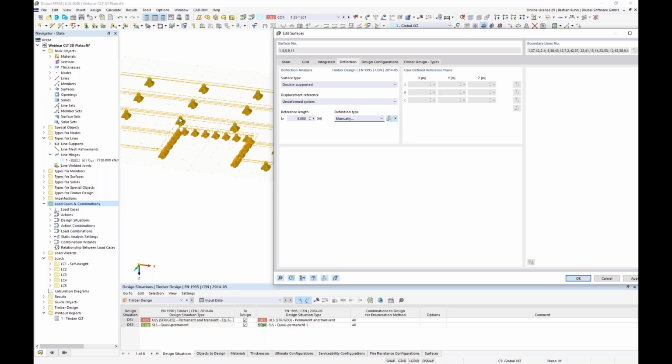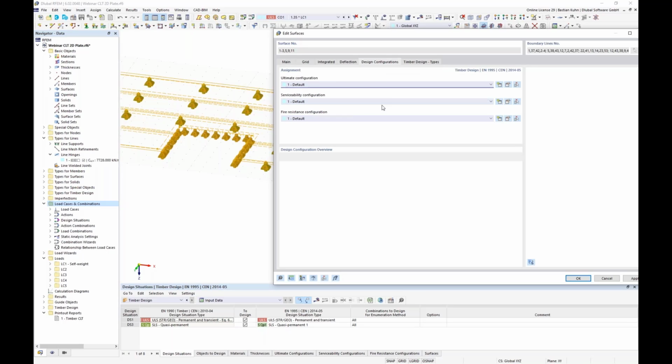But how do you want to regard it with this other side? Therefore I choose 5 meters, because I'm choosing the difference between this point here, and you cannot see it now in here, but the other point there. So to me, that is now on the safe side. And if deformation gives me problems, I anyway would have to do a more detailed deflection analysis. Okay, I hope that explains it a little bit.